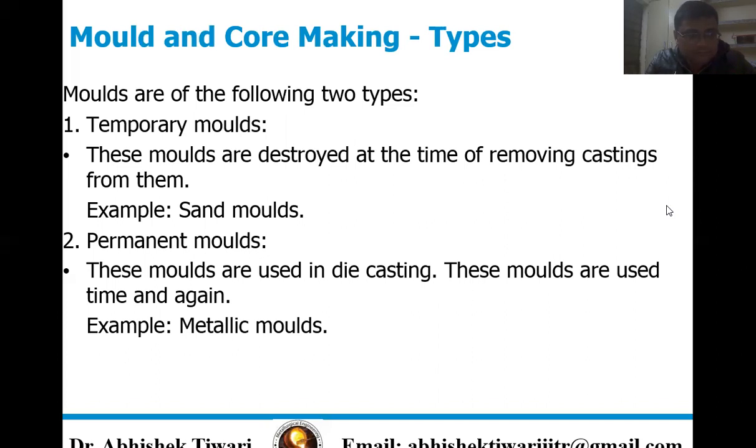Additionally, chemically bonded molds have been developed that are not based on either of these traditional binder ingredients. Some of the binder materials used in these no-bake systems include furan resins consisting of furfural alcohol, urea, and formaldehyde, phenolics, and alkyd oils.